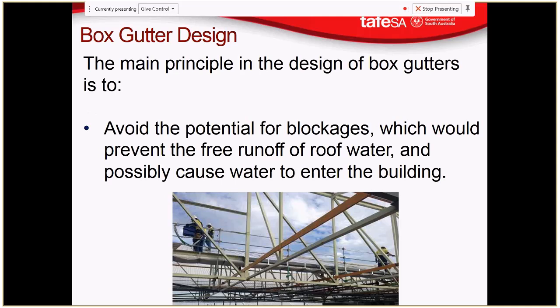So when it first starts to rain, it picks up all the dirt and grit and so on out of your gutters, and that goes into this pipe here. That ball floats up to the top when it gets full, and all the water then flows down there. So the first bit of water to come off your roof, with the bird poo and things like that, goes into this pipe here, and then through the small hole at the base, it drains out slowly. So over the next couple of hours, that drains out and the ball goes back down again.